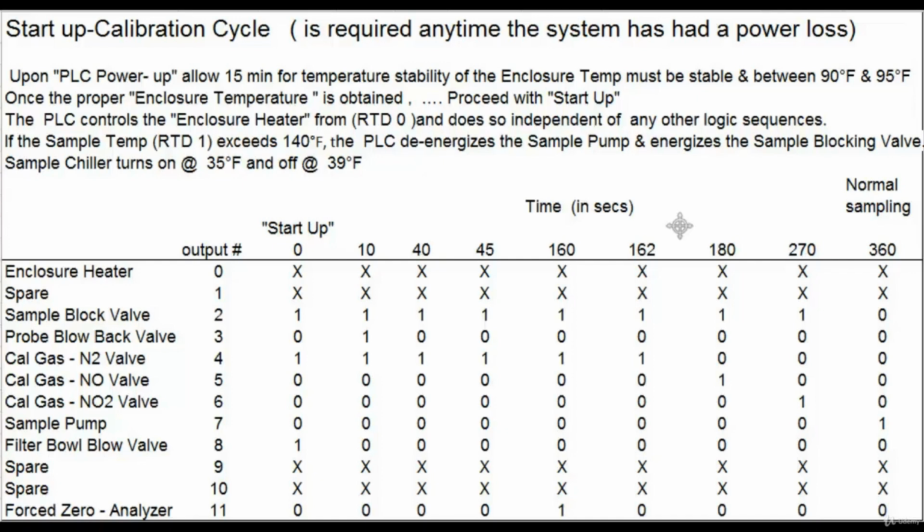There's a saying that writing clarifies thought, and it's true. When we look at the document on the screen, it's nothing elaborate, it's nothing too highly structured, it's a simple Excel spreadsheet. But it tells us in time exactly what needs to happen and when we're starting up a system. And it's hugely important to have something like this in front of you when you're writing a PLC program. A lot of us can do it off the top of our head, and we get a little cocky about doing that. And more times than not, we spend far more time than we should shaking down and debugging a program before we can load it onto a machine and hand it off to somebody.